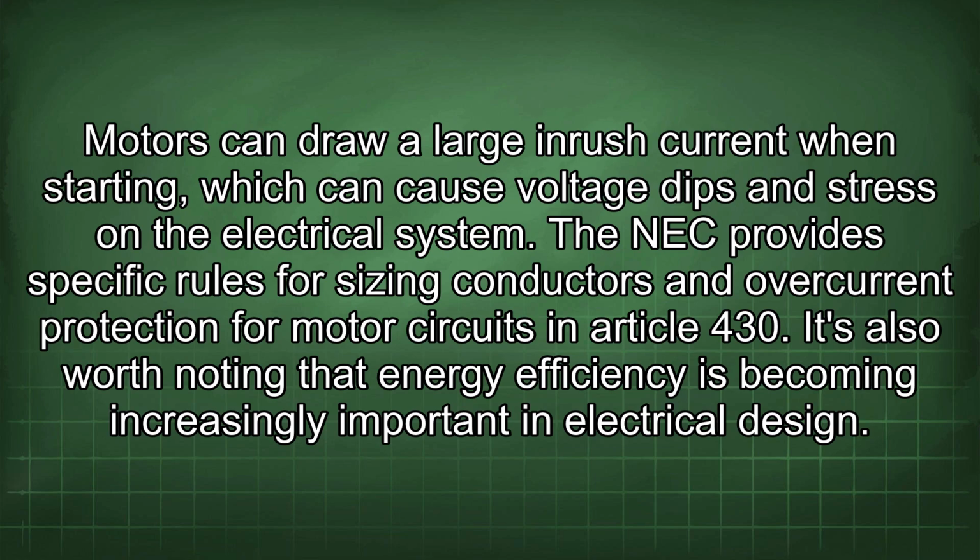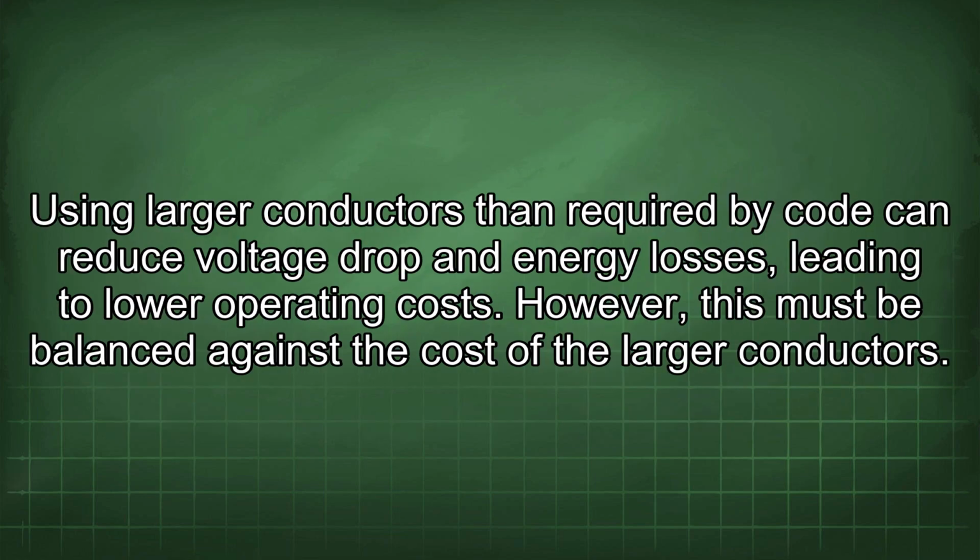It's also worth noting that energy efficiency is becoming increasingly important in electrical design. Using larger conductors than required by code can reduce voltage drop and energy losses, leading to lower operating costs. However, this must be balanced against the cost of the larger conductors.